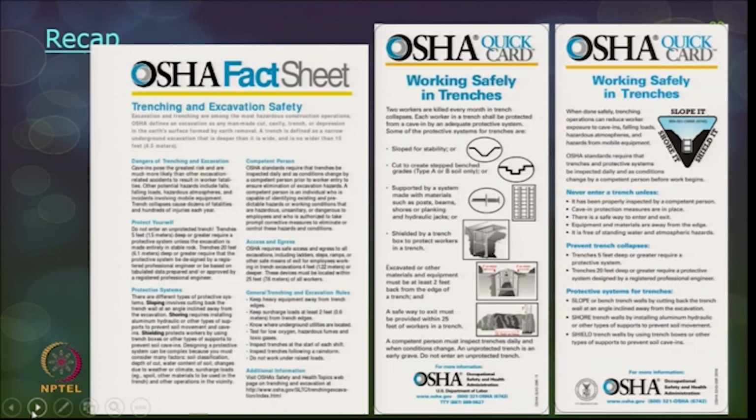Cave-in protection measures should be in place, and there is a safe way to enter and exit. Equipment and materials should always be away from the edge, and the trench should be free of standing water and atmospheric hazards. Prevent trench collapses. Trenches 5 feet or deeper require a protective system, and trenches 20 feet or greater require a protective system which is designed by a professional engineer. Sloping or benching, shoring and shielding are the 3 protective systems available.